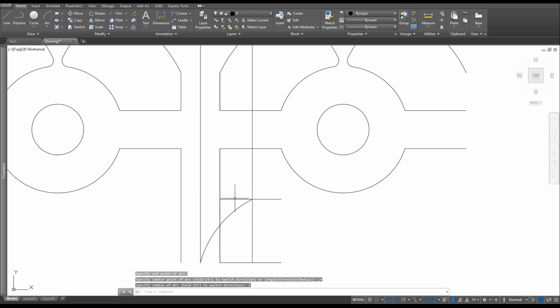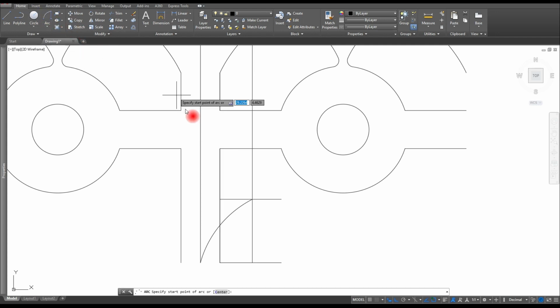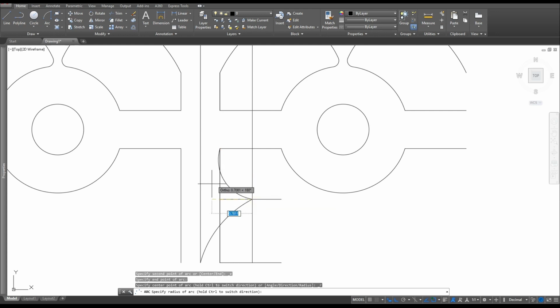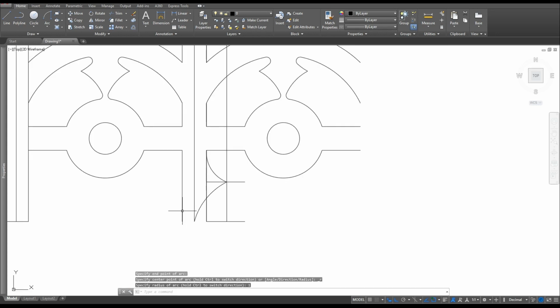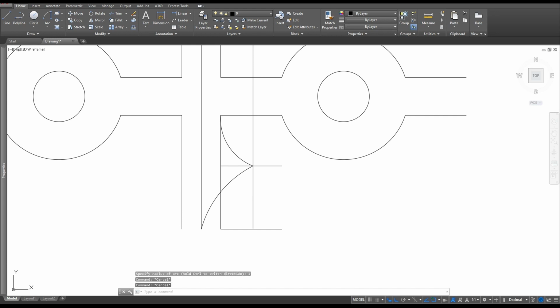And then the next thing I need to do from this one is I have an arc that's going down from here and it's going to here, and it has a radius of 1. So my start, end, radius, I'm going to create that circle in a counterclockwise rotation. So I'm going to start here and then to that intersection, and now that one has a radius of 1. So I do have my shape actually created now. Go ahead and delete some of these lines.